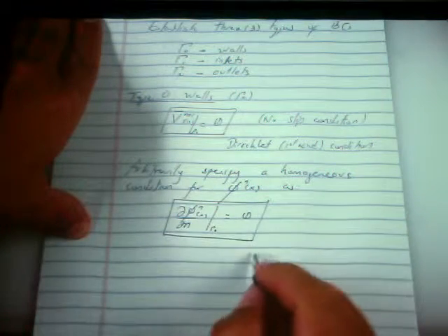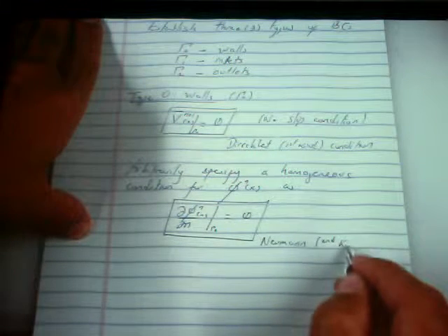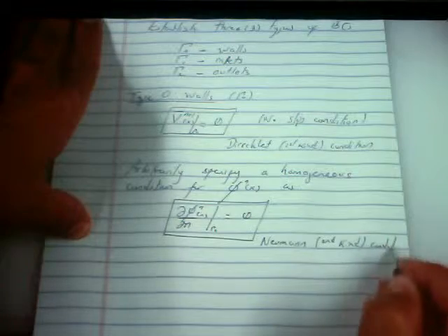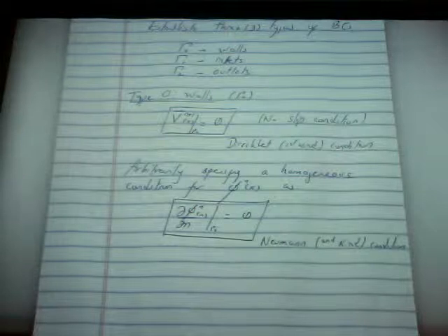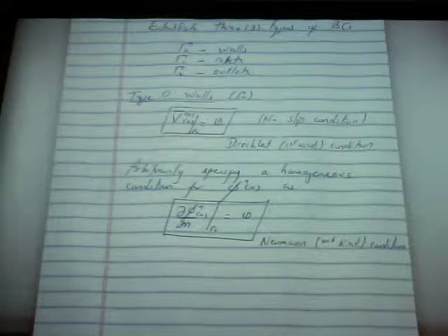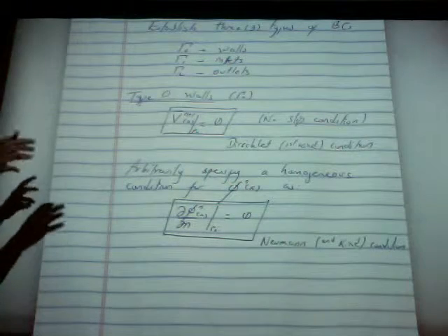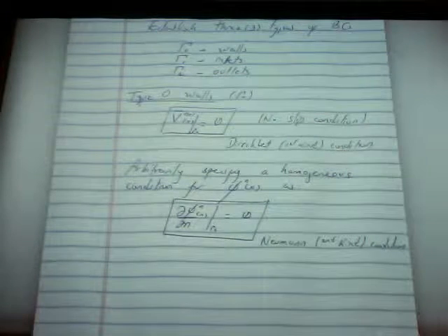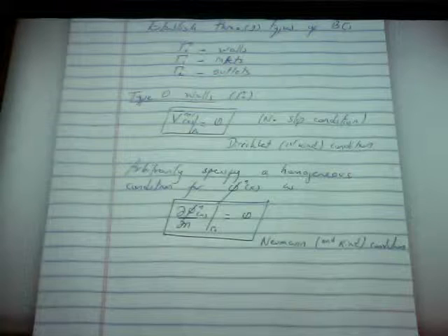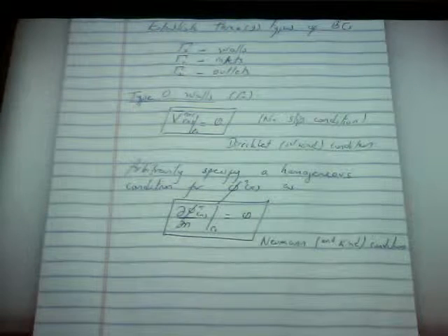And as you can see, this is a Neumann, second kind condition. So phi is kept at 0 normal derivative. Okay, there are implications to that. We're arbitrarily saying this, but it's not so arbitrary. There is an explanation of why this one would have 0 normal derivative. It implies the normal derivative of the pressure doesn't change. It implies other things, but mainly, I'll tell you at the end, once we set up inlets and outlets. So we have walls.